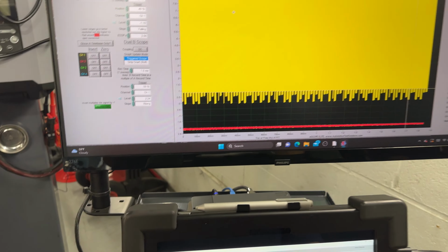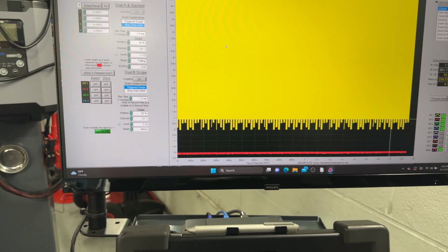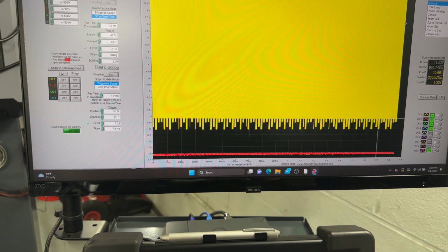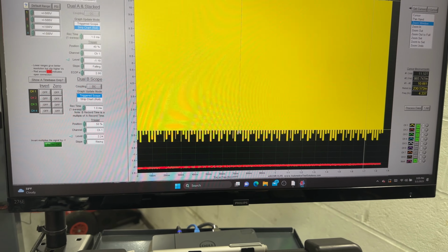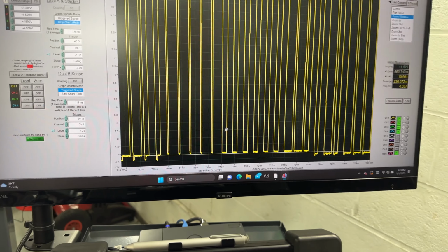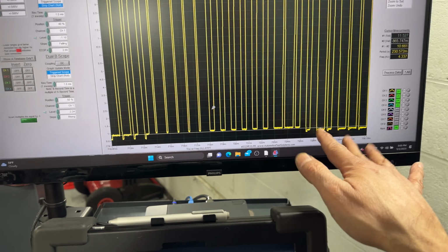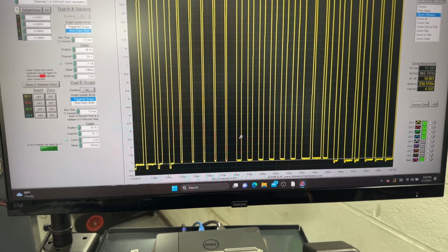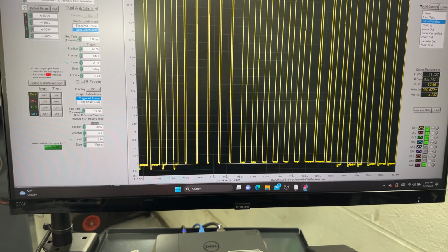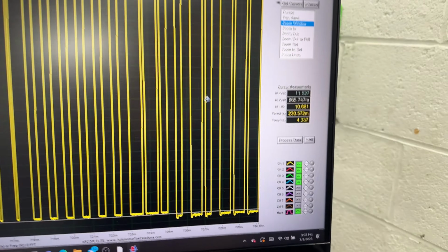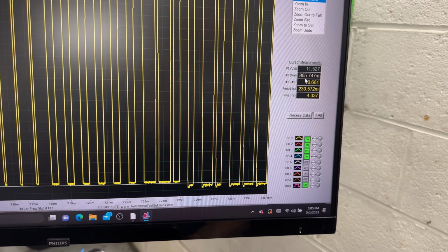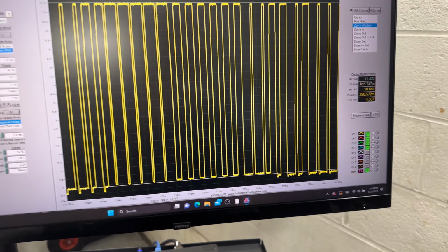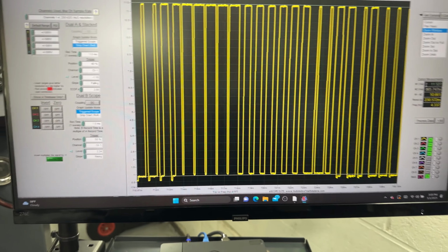All right, but if you're using it just to see one signal, let me see if we really see a big difference on the capture. I really doubt it because, as you can see, we can definitely see the signal a little hashy, but it's good. You can see it's reading around 11.5, and cursor 2 is around 865 millivolts. Remember the positions of the cursors.